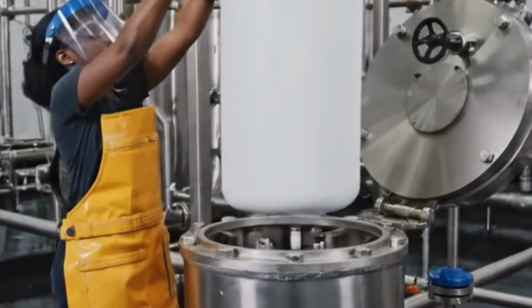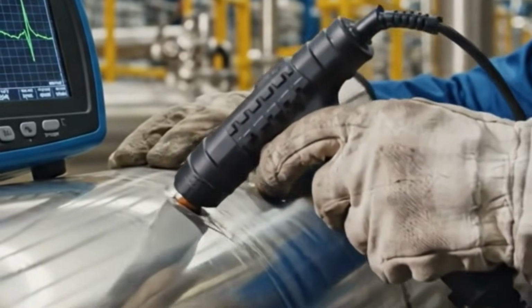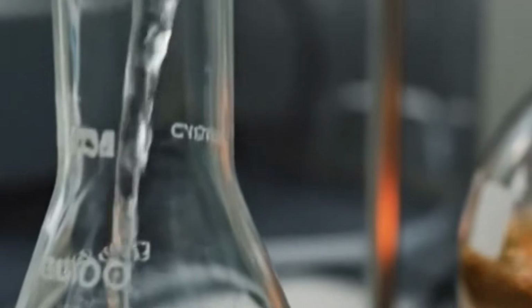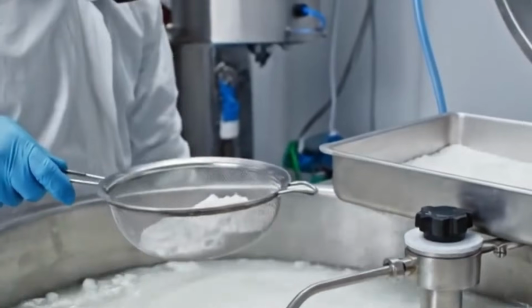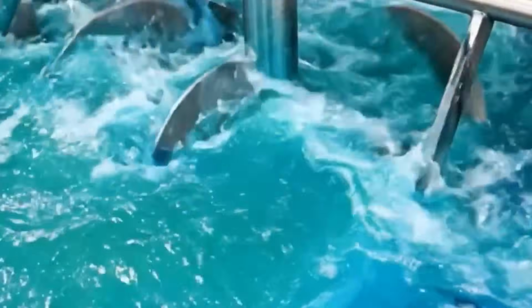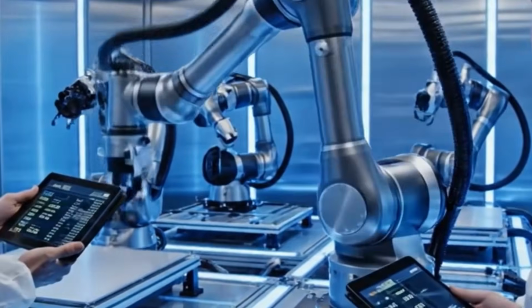These are introduced as aqueous solutions prepared in separate blend tanks. Preservative concentration ranges from 0.05–0.2% depending on product shelf life requirements and microbial load assessments. Addition is carried out under agitation to ensure full dissolution.